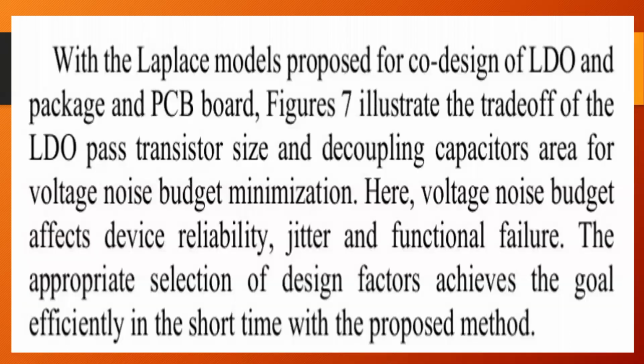With the Laplace model proposed for co-design of LDO and package and PCB board, figure 7 illustrates the trade-off of the LDO pass transistor size and decoupling capacitor area for voltage noise budget minimization.